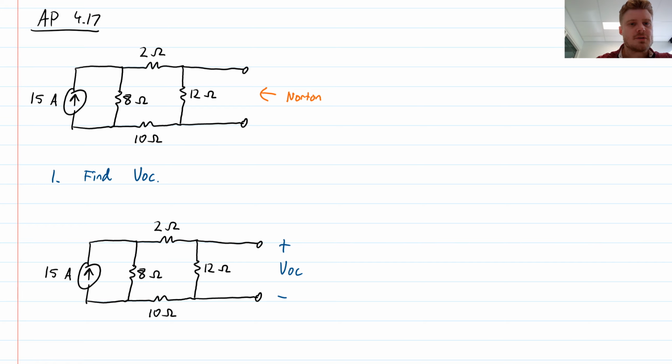I could do a nodal analysis where I could define, say, a reference node and then work from that. So define a reference node here, define a node, and then another node, and then another node, and proceed in that way to do the analysis. But that one will probably take a little while because there'll actually be quite a few nodes there. So a simpler way to analyze this would be actually to do a mesh analysis.